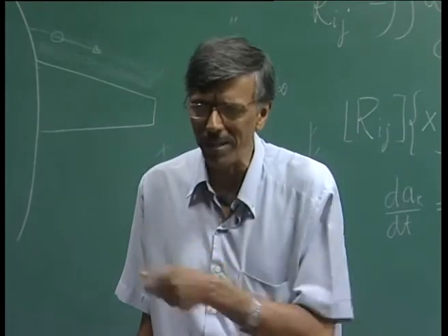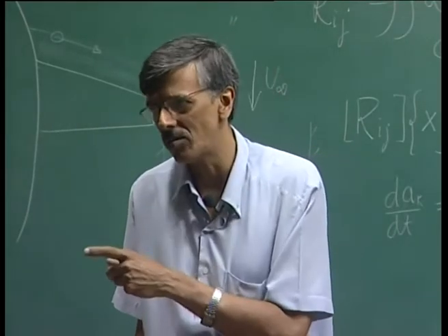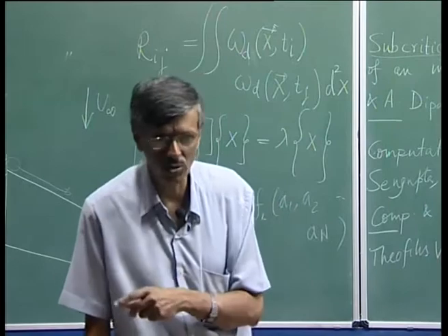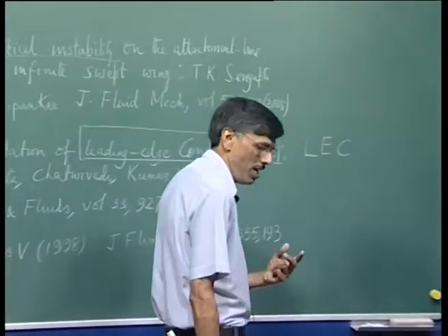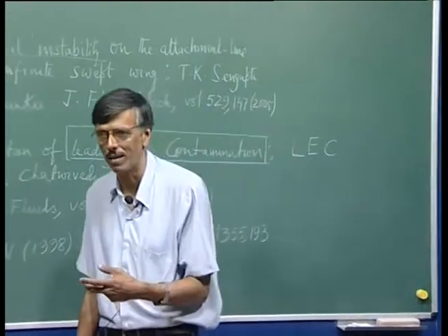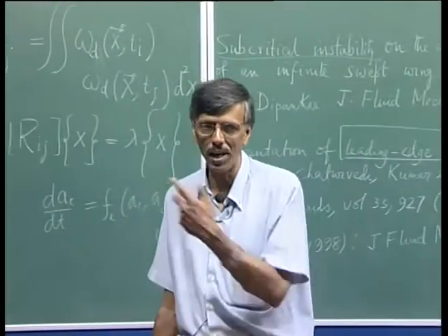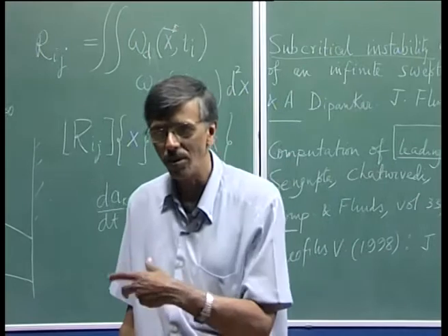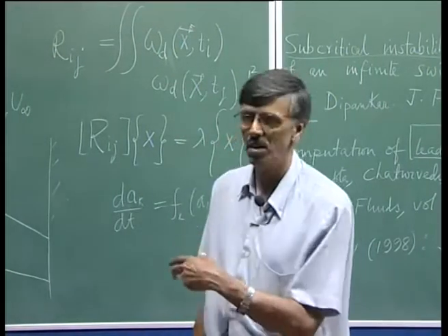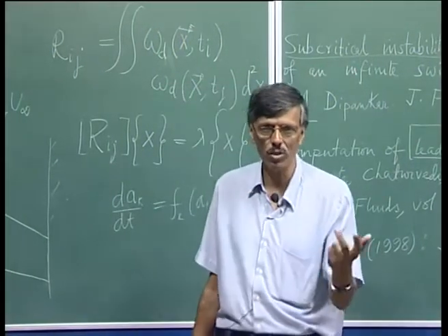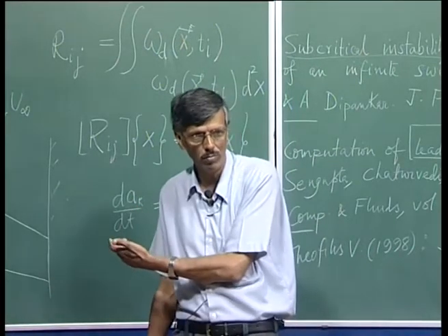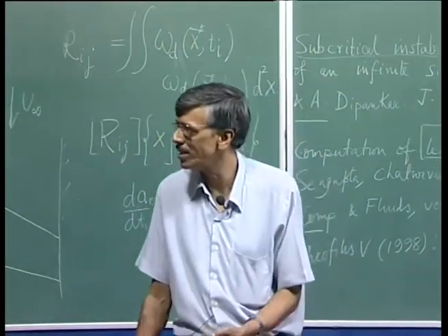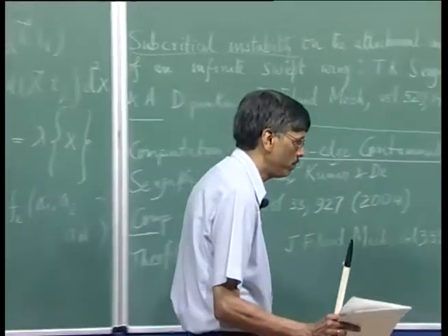This predominantly happens if your sweep angle is more than 20 degrees. Many a time you will hear people say that if we do not have a sweep angle less than 20 degrees, then we have 3D instabilities. So, with less than 20 degrees, you have a transition going from 2D stagnation point flow to attachment line flow. Okay? So, this is something that we must remember.